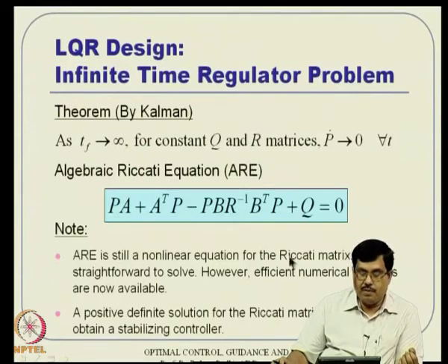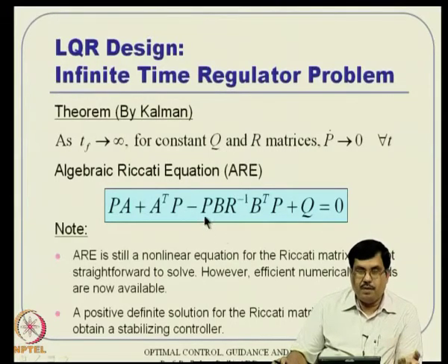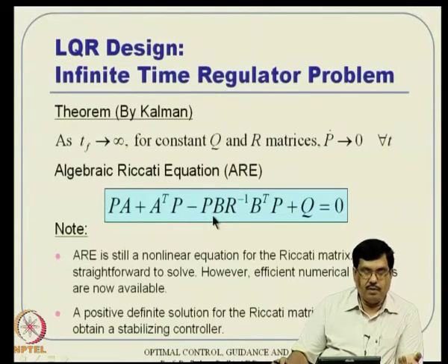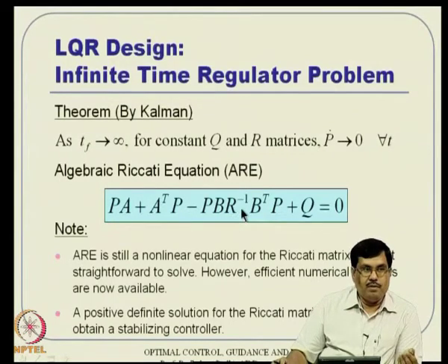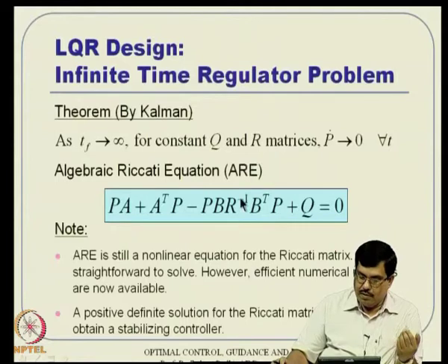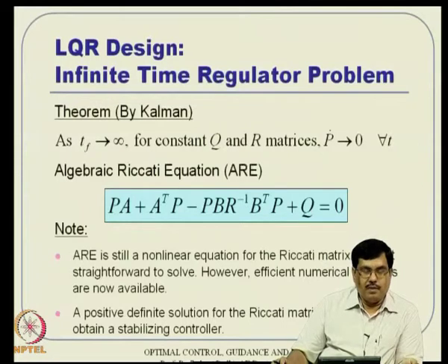But because this equation keeps on appearing in a number of problems across the field, people have done a lot of research on how to come up with efficient numerical methods. It is all available now, and some of these have also gone into routines of the Control Systems Toolbox in MATLAB. There is a command called ARE for the algebraic Riccati equation, there are commands for LQR also, LQR, LQR2, then discrete LQR, DLQR. So, there are a bunch of functions available in MATLAB.